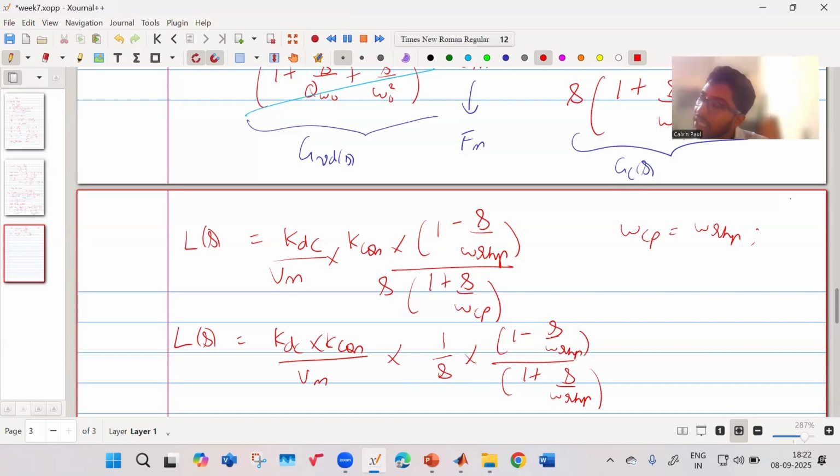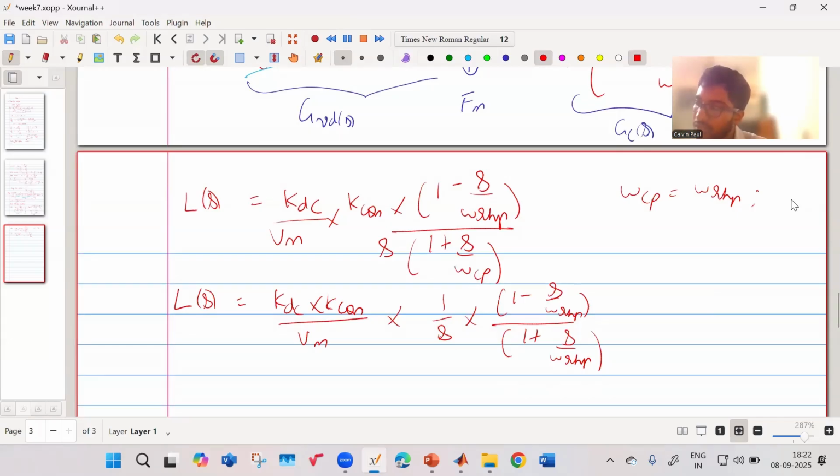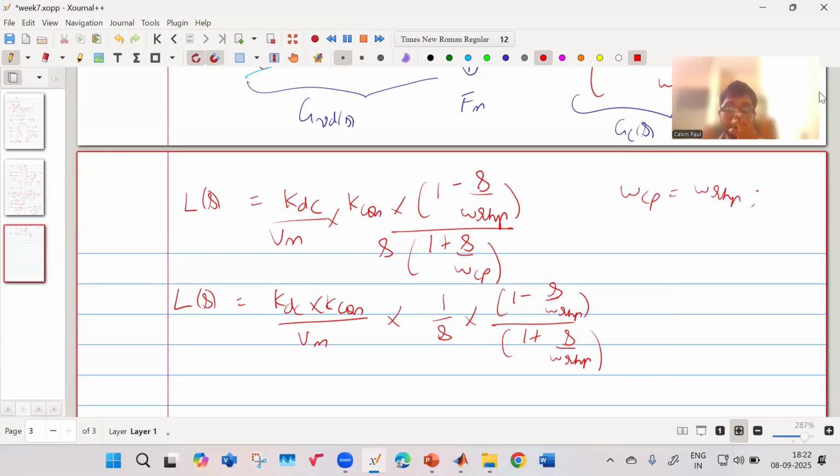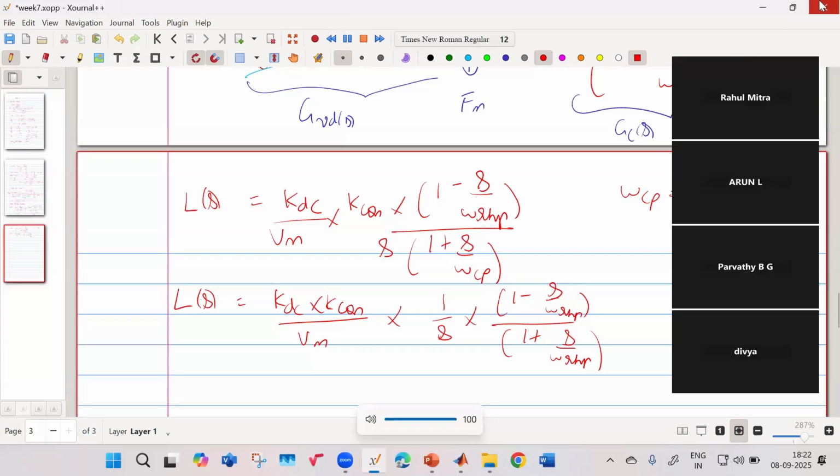Okay, why didn't we place our controller with 1 minus? Because we should not. It would result in some, as sir had mentioned, internal instability. So that we don't do. So we place our omega controller pole in coincidence with our omega RHP. So what is the benefit of this? What do you think will happen? The omega RHP will get cancelled. The zero is not getting cancelled, it's there. The magnitudes will get cancelled. Yes.